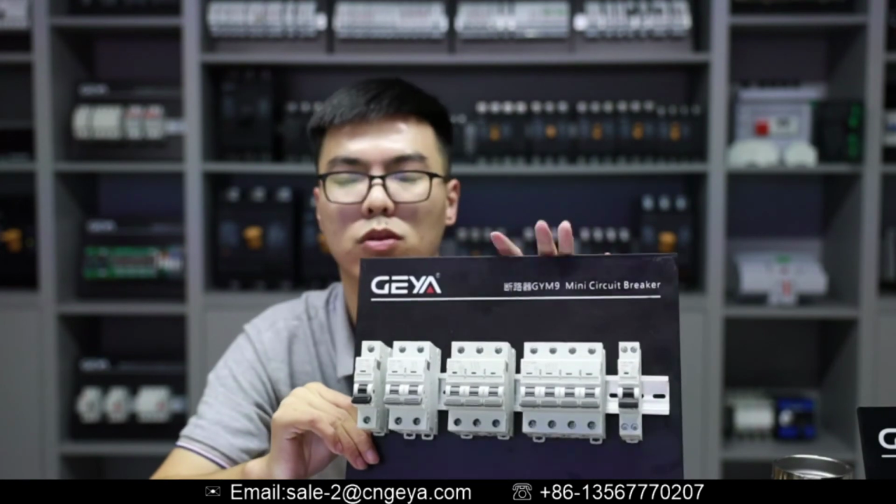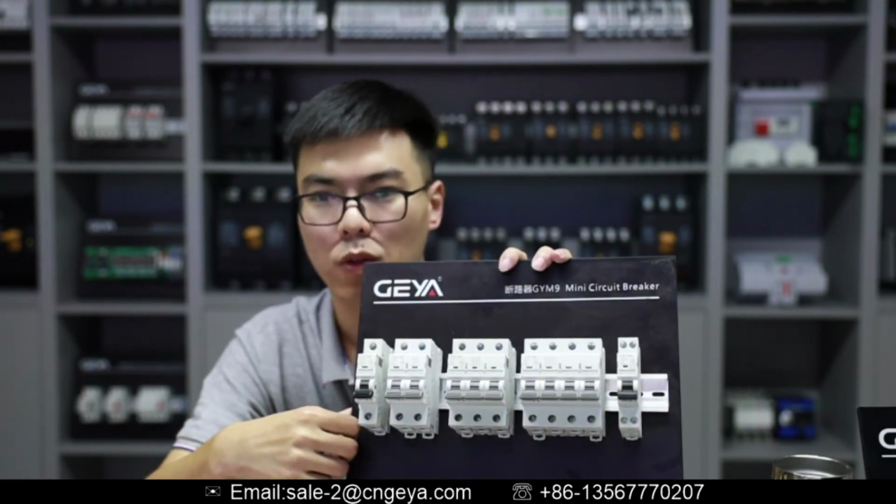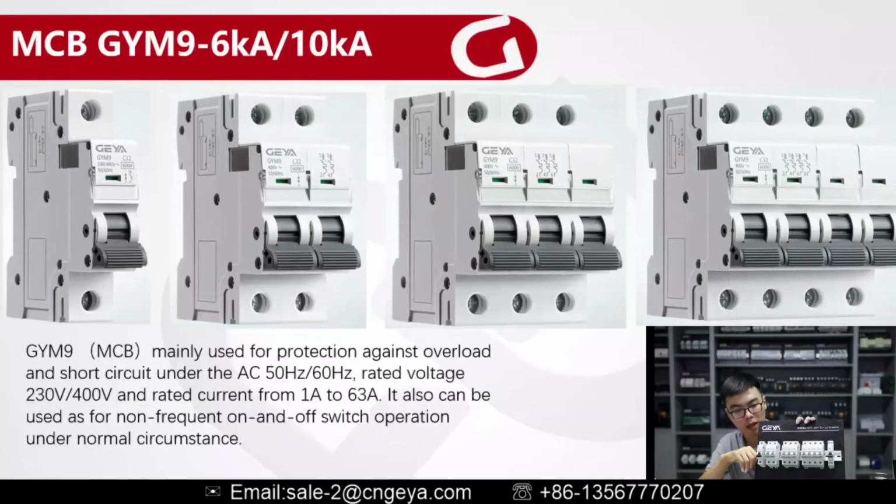It can also do from single pole to 4 pole, and the rated current from 1 ampere to 63 amperes. This type of body structure is a C65, different to the previous items.